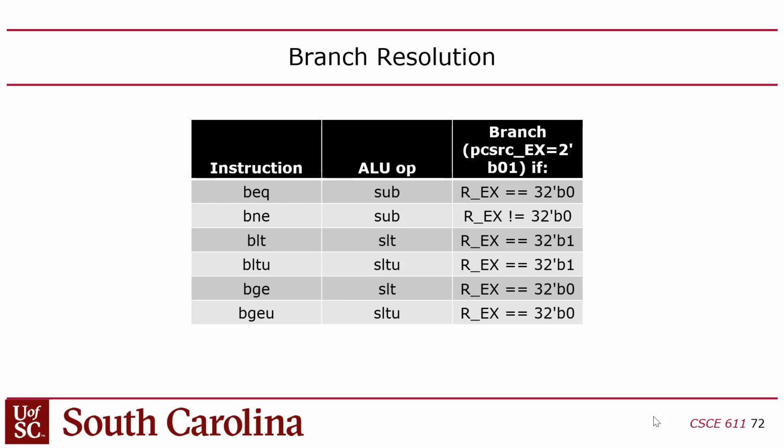So the assembler could take care of that. Does it make sense? I think that's how it works. I don't know if I ever tried that, but I'm pretty sure that's how it works. Of course, you could do it in hardware too. If you added mux inputs to the ALU to allow A and B to be swapped, then you could handle that in hardware, but then you'd add extra delay because you'd have more inputs on those muxes. There'd be a cost associated with that. And the RISC-V guys are trying to make this thing as fast as possible, so that's not the approach they want to take.